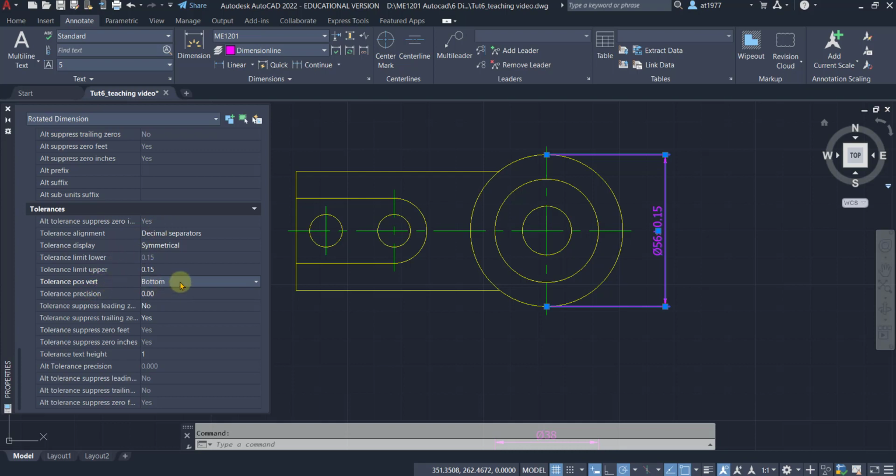Tolerance position vertical. Usually we just leave the default as bottom. Precision is 2 decimal places. If you want more, you can change this. Alright. Last but not least, the text height we want to be 0.8, which is a scaling factor. Alright, so what do we key in? We key in this tolerance text height, which is usually 0.8 times. Alright, the limit of the tolerance and the type. Also, last but not least, alignment.